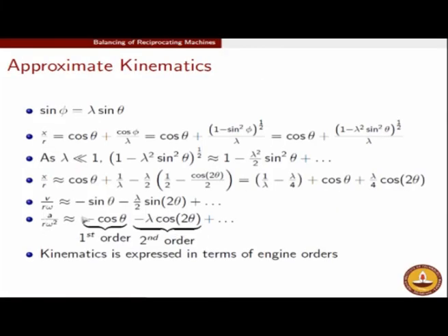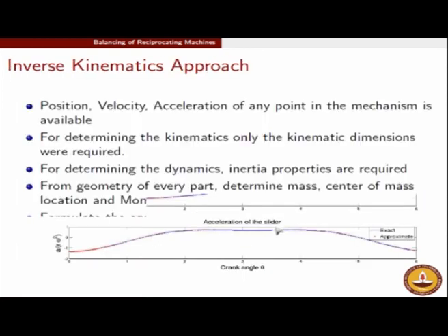Okay, DCRU is asking how we can write x double dot in the form of lambda and omega. That was what was done yesterday. If you recall, we had obtained the approximate expressions for acceleration in yesterday's class. This is x double dot, the acceleration of the piston in terms of the angular velocity of the crank, so this is exactly what we have referred to. In slide number 31 you will see how the acceleration of the piston is related to the crank speed. Fine. If there are no other questions, let me continue with multi-cylinder engines.